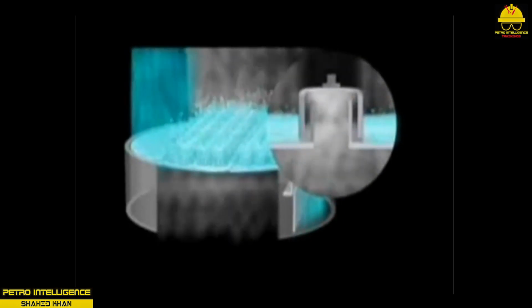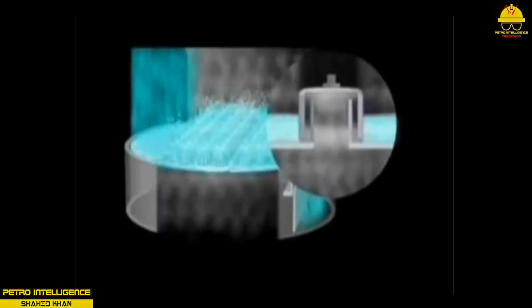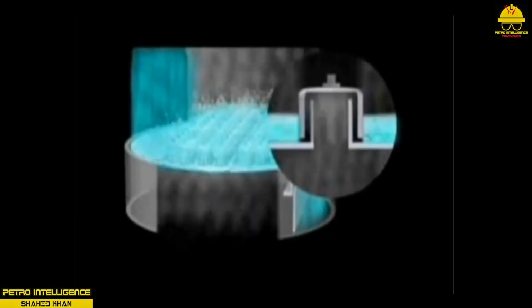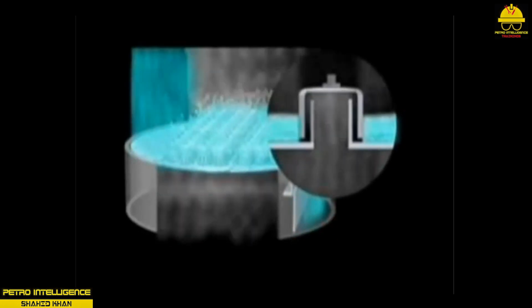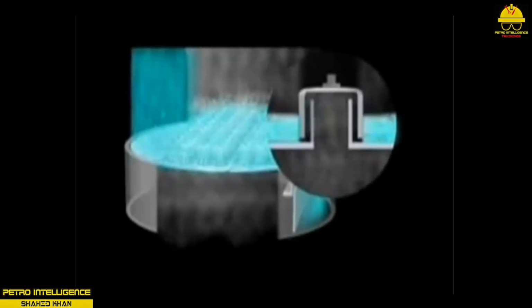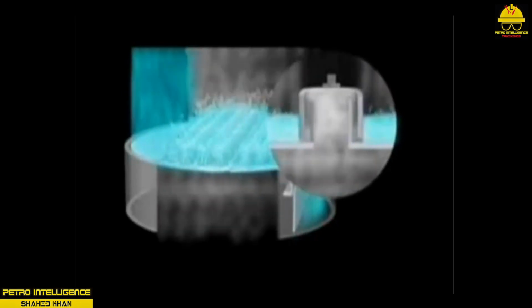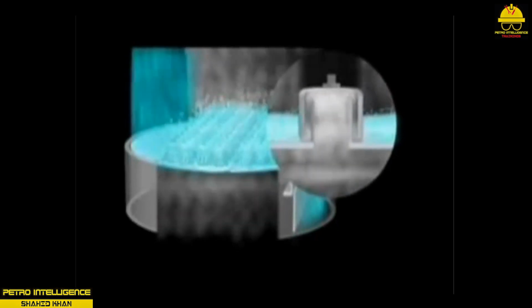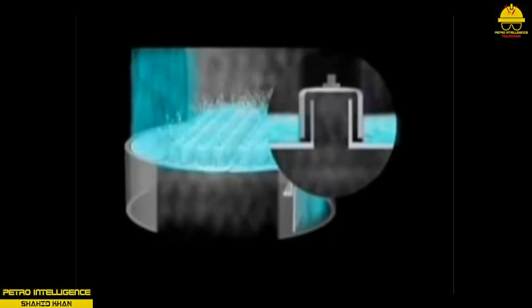Slots notched into the side of the cap enhance vapor and liquid contact, as shown in the picture. This vapor comes into direct contact with the liquid on the tray and transfers some heat energy. The liquid condenses the heavier components of the vapor, whereas the lighter components move up the tower. A weir on the tray maintains a liquid level over the caps. As heavier condensate builds up, it flows over the weir and out a device called a downcomer. The downcomer discharges onto the tray under it.